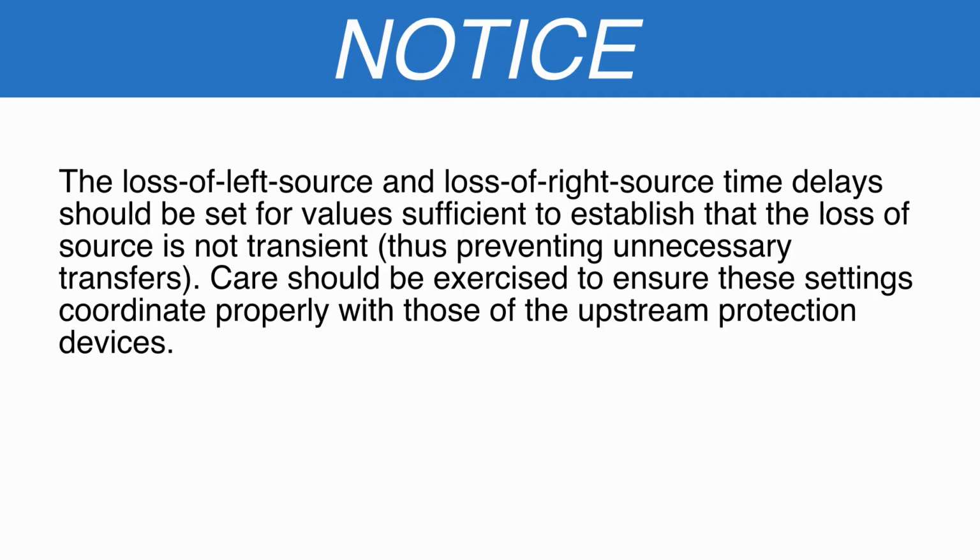Notice, the loss of left source and loss of right source time delays should be set for values sufficient to establish that the loss of source is not transient, thus preventing unnecessary transfers. Care should be exercised to ensure these settings coordinate properly with those of the upstream protection devices.